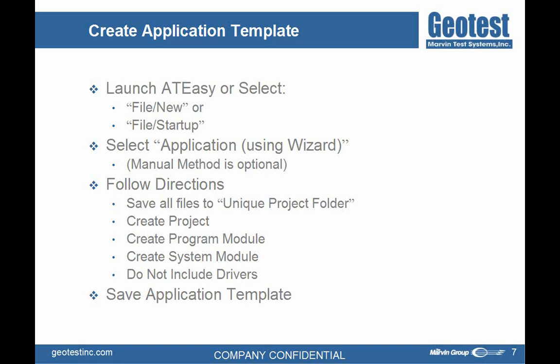And then we're just going to follow the directions for that wizard. We're going to save all of our files to a unique project folder. We're going to create projects, program module, system module. We will not include any driver modules at this point. We'll add those in later, and then we'll save that template.